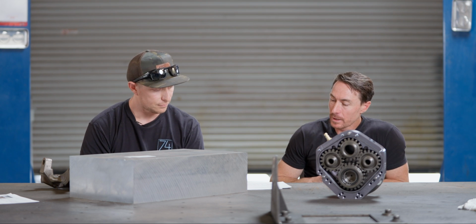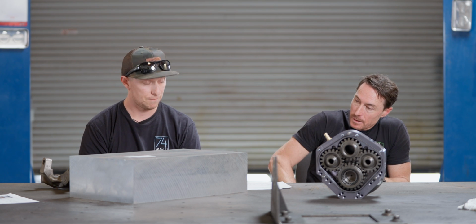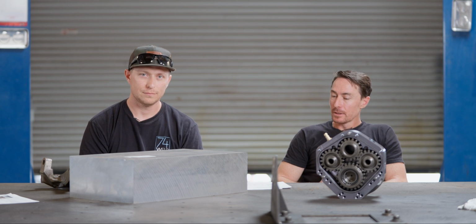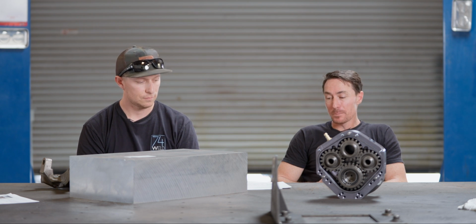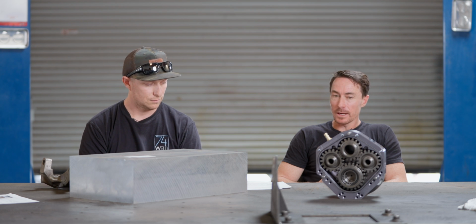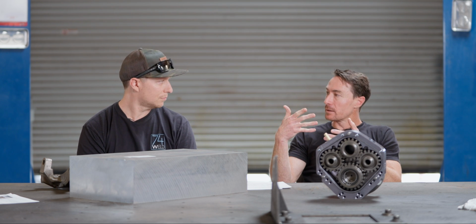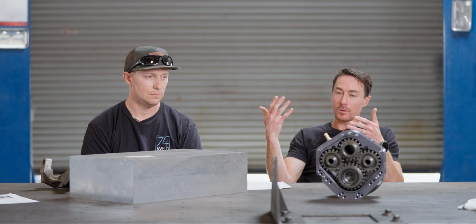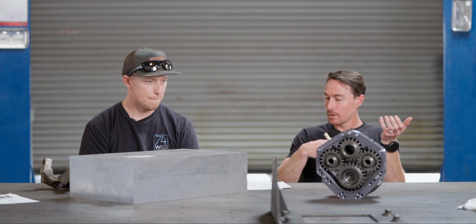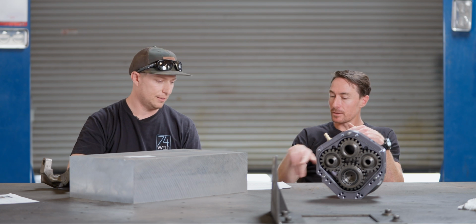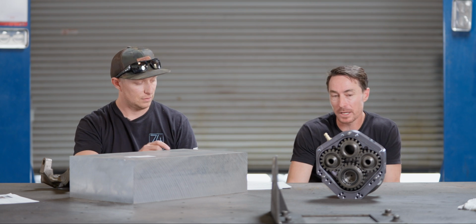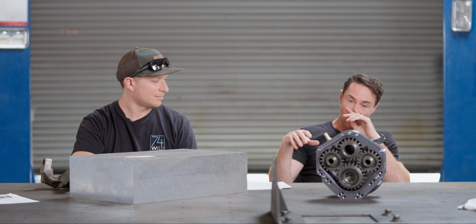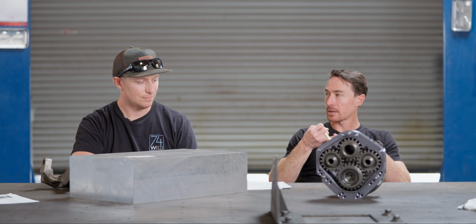One thing that's worth noting is elongation properties. 7075 is not an extremely elastic material. It has an elongation of up to 11%, so it can bend 11% before it ultimately will take a different form. 6061, before it breaks, is 18%. That really comes from some of the mechanical properties of the alloy itself. It's got a high zinc content.